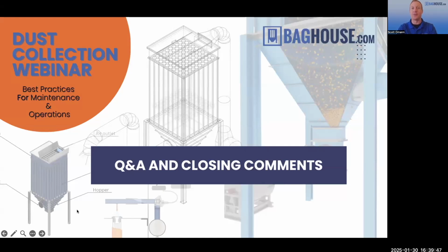Wear out that filter, we have to change it, we have to change out this, we have to change out that. It just becomes a vicious cycle of we just need to change out all of our filters to make sure the baghouse is functioning correctly. Yeah, exactly. We actually say a lot of times it leads to cascading failures, right? If you keep doing it.